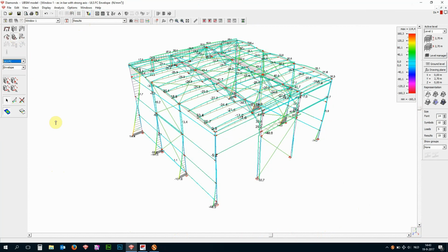In order to decide if the structure is okay, yes or no, we need to check 3 things. One is the stiffness. Now, this means is the deflection within the acceptable range? Each design code has its limits for the vertical and the horizontal deflection. It's up to the user to verify that the current deflection is allowable. Let's assume that the limit for horizontal and vertical deflections is span divided by 300.